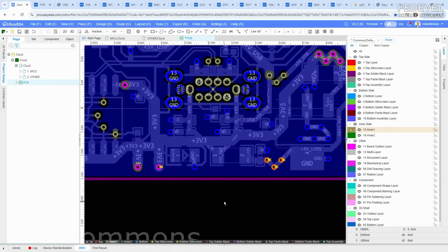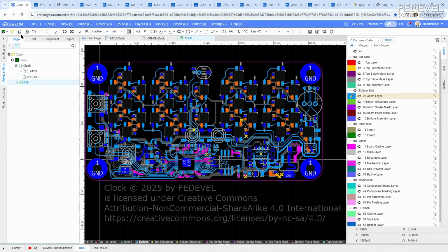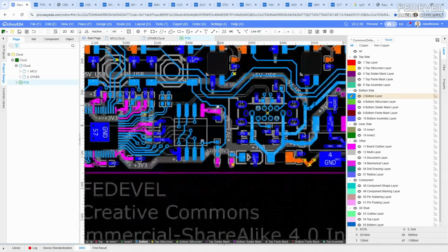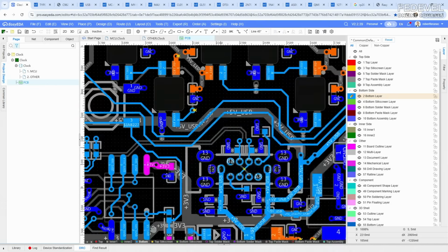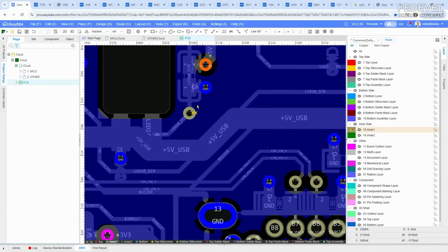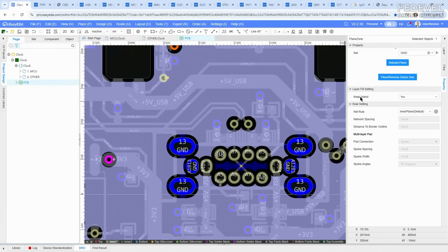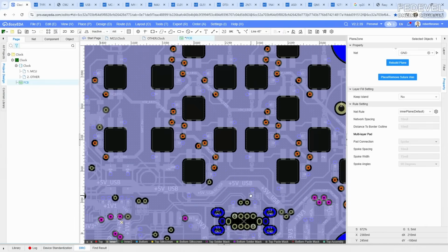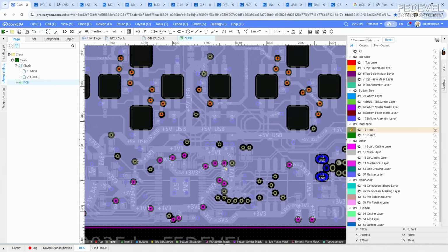There are actually a number of errors connected with ground planes, which are inside of our PCB. Most of these yellow marks, which you can see here, are connected with not updated ground planes. So go on ground plane and notice we need to create space around these vias and we have to remove this. It's called island. So keep islands, no, and now see what happened. So the plane was rebuilt, refreshed, and also all the new vias now have space around them. So everything is okay, but here is something.